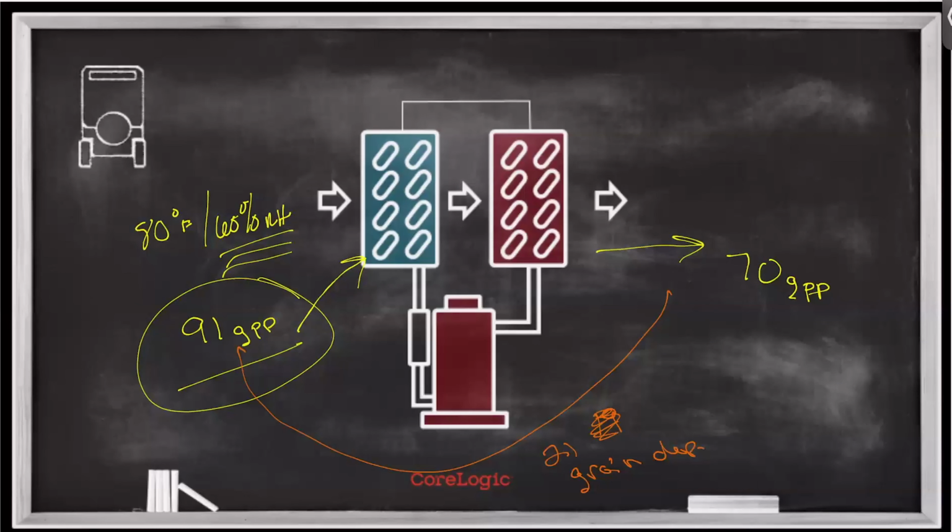Now, what does that mean, right? Is that a good performing dehumidifier? Is that a bad performing dehumidifier? That number in and of itself doesn't really say a whole lot to us, right? Now, to understand what that number actually is, I'll give you the technical definition, which I don't expect to give you a whole lot of understanding, but I want to share it with you. That means I'm removing 21 7/1000ths of a pound of water for every pound of air processed by the dehumidifier. Does that tell you anything? It doesn't tell me anything. I know exactly what it means, right?